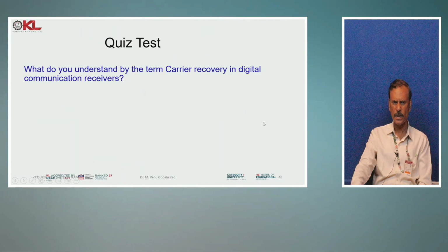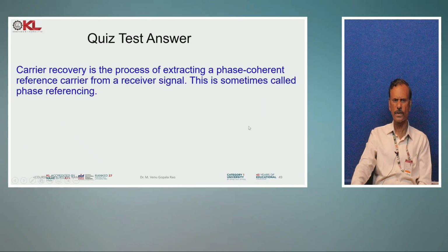So this is a quiz test. What do you understand by the term carrier recovery in digital communication receivers? The answer: carrier recovery is the process of extracting a phase coherent reference carrier from the received signal.